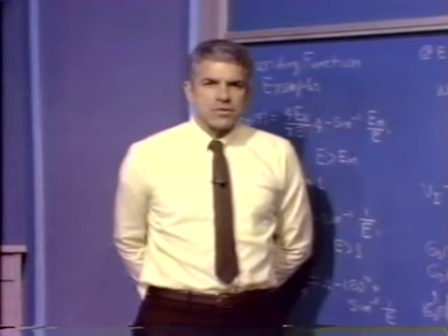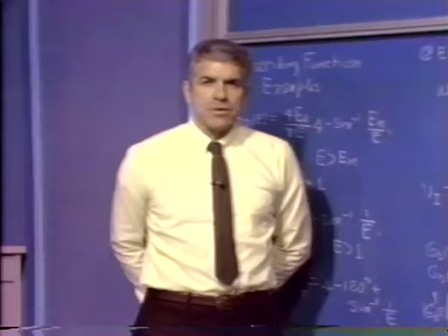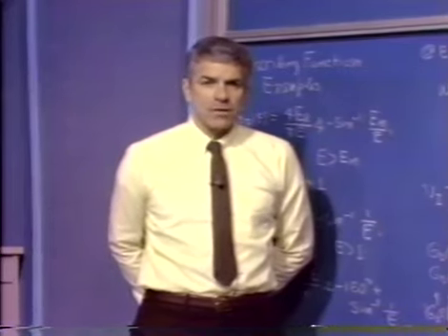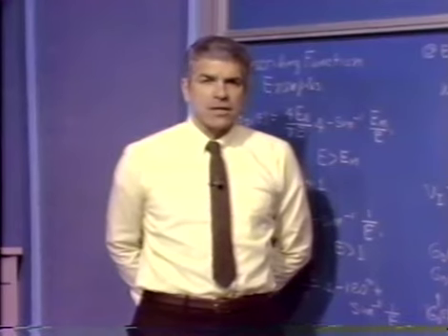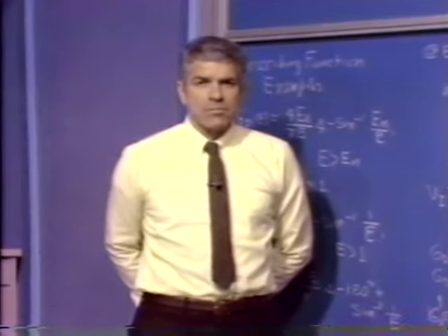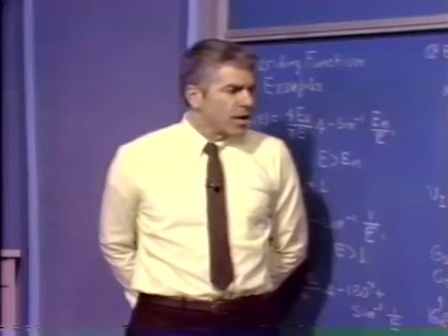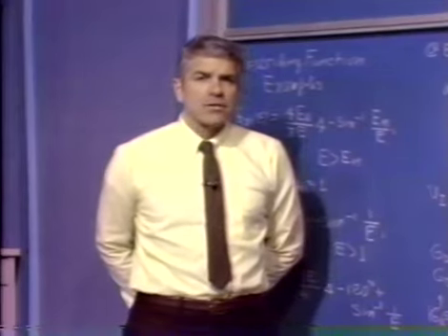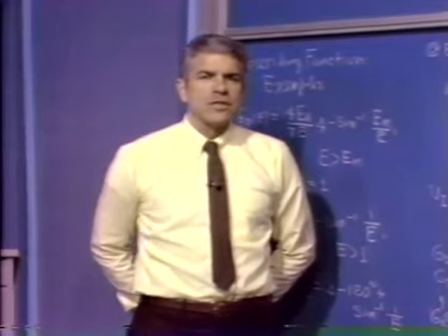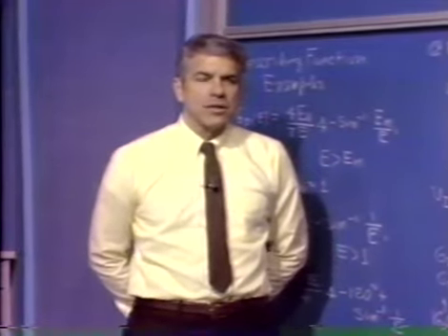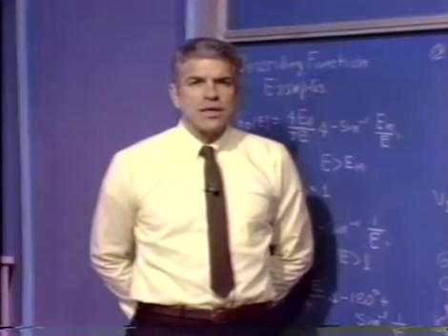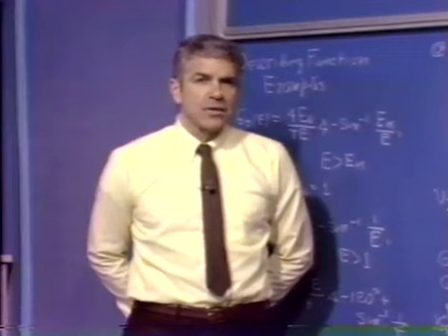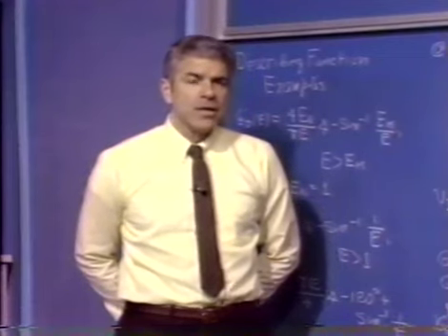The describing function analysis predicts an amplitude of 1 for the fundamental component of the signal into the nonlinearity. The actual fundamental component is about 0.8. The reason is that one of the difficulties with the analysis, aside from the fact that there's not a good, clean, crossing kind of intersection in the gain phase plane, is that there's considerably more harmonic distortion in this case than there was in our earlier example.